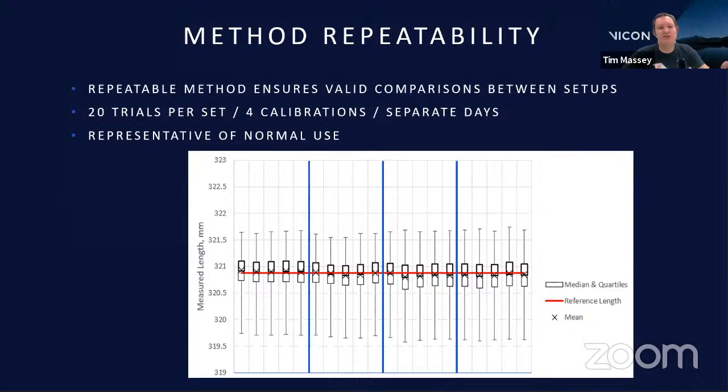Do you provide it with enough disparate data to achieve a really good calibration? So the technique of waving the wand, in most cases, is perfectly adequate. There are some techniques where you don't collect that good array of data around the camera lens, and that may adversely affect the calibration. So a combination of number of frames, but also the quality of that data you're providing to the calibration algorithm to give a good calibration is always beneficial.